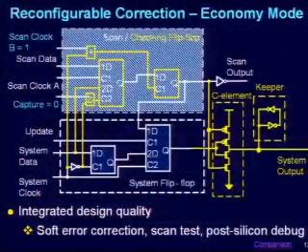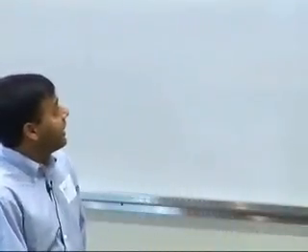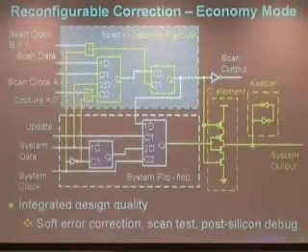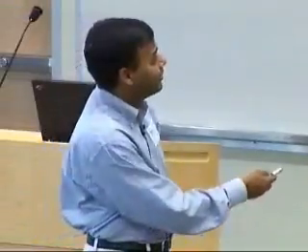There is another benefit of using a technique like BISER that I was showing before, and the benefit is that you can turn protection on and off. Here is a flip-flop design that's inside many of your processors. This is Intel's scan flip-flop design, and Intel implemented a scan flip-flop in this particular way so that while the system is running, they could scan out the contents, which is a snapshot of the system, without having to stop the system. This was very useful for post-silicon validation purposes, and that's why they had this paired flip-flop.